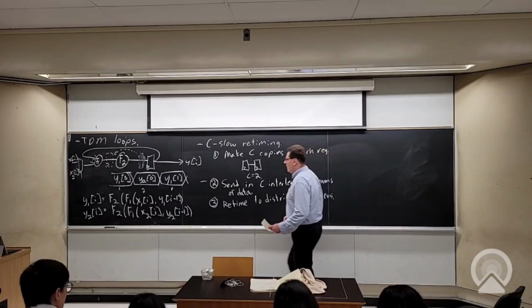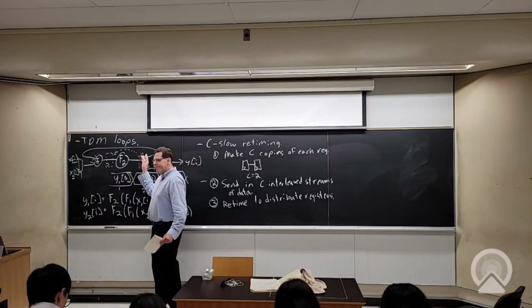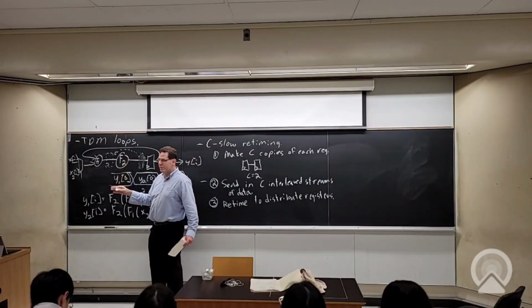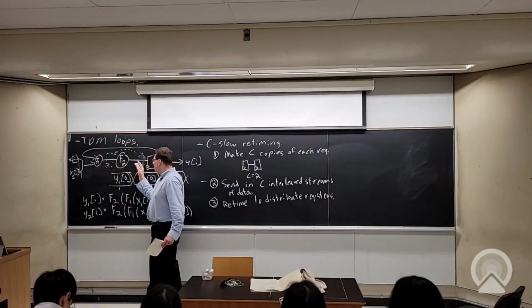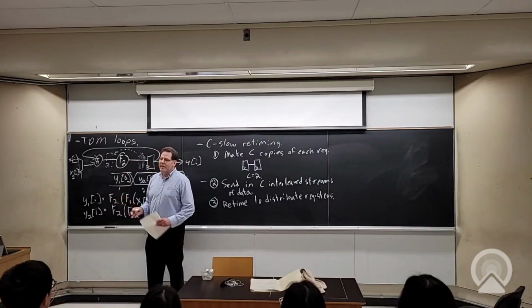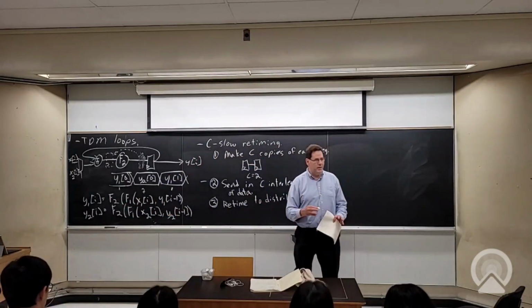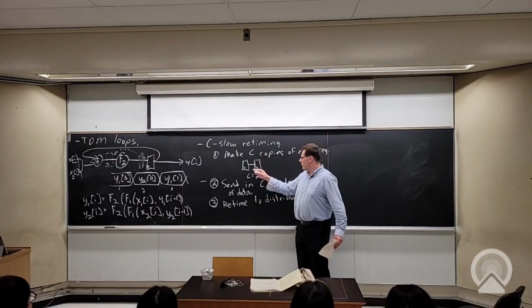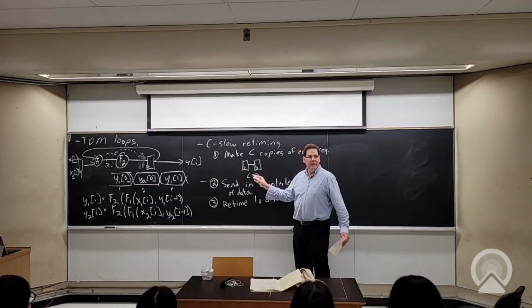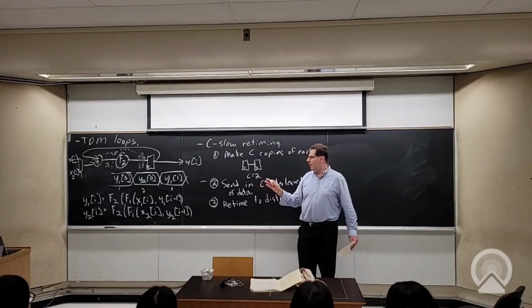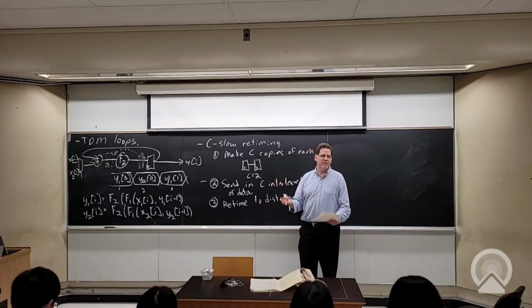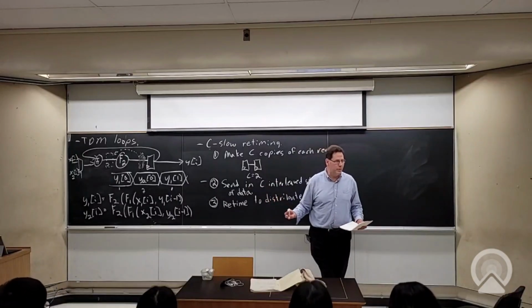When I put this up originally, I essentially did those 2 steps in 1 step. I actually put an extra register here, which is already in kind of the right spot. In a more complicated design, it might be hard to see that, if I have registers all over the place. So a mechanical procedure like this that says, double them all, now go and retime them 1 by 1, is a recipe. You can do it with less worry about breaking the circuit.